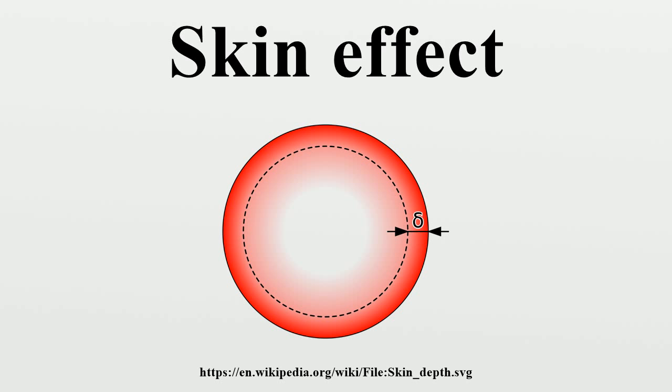Examples. We can derive a practical formula for skin depth as follows, where the skin depth is in meters, the relative permeability of the medium, the resistivity of the medium in ohm meters, also equal to the reciprocal of its conductivity, and the frequency of the current in Hz.